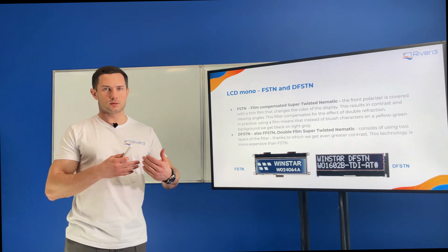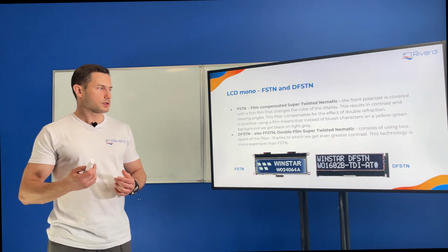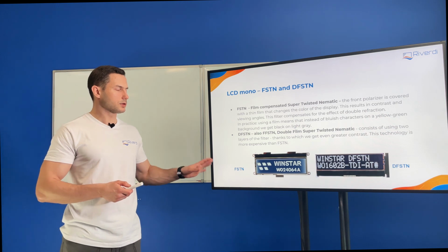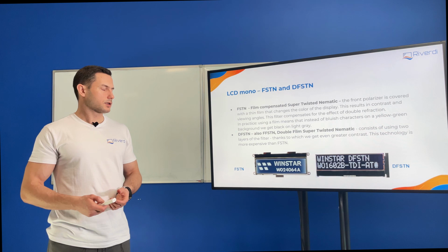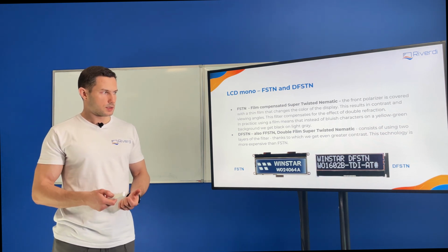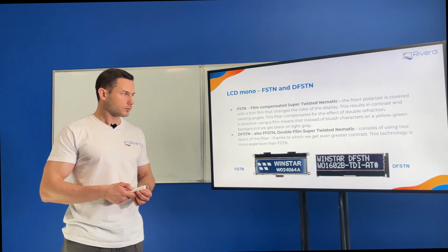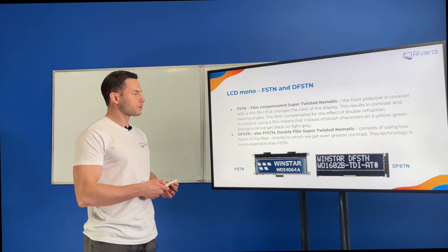Yes, if we want to see the display from the angles, there are other technologies. Of course, TFT is one of them, or OLED technologies that are way better than the monochrome displays. But monochrome displays are very popular still, because this technology is well known, established, and cheap. Yes, so these displays are usually the lowest cost displays that we can buy on the market.